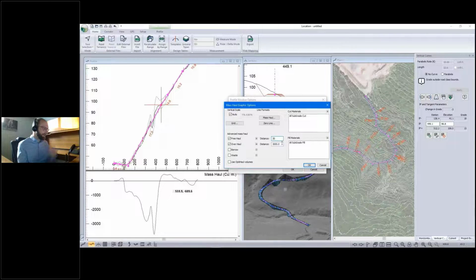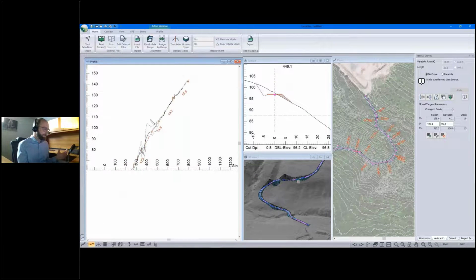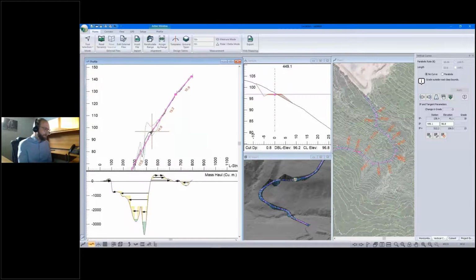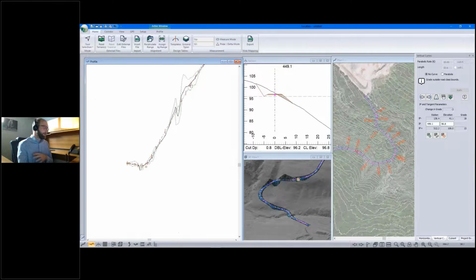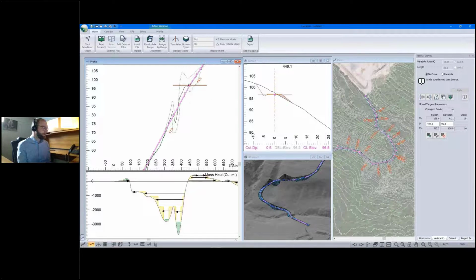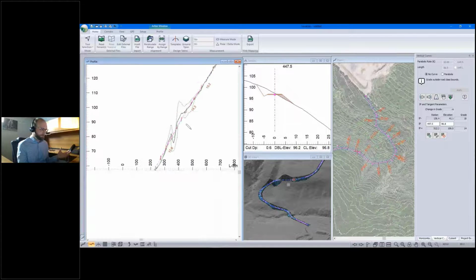And I can add some graphics here to see what's going on for that mass haul material movement. And in this case, with that balance that I'm doing, it makes sense. We have to go through a steep section. It's going to be full bench. That is what it is. But right before that, I've got a switchback, a nice broad switchback. But I can use the cut material from that as a fill to help minimize my grades.